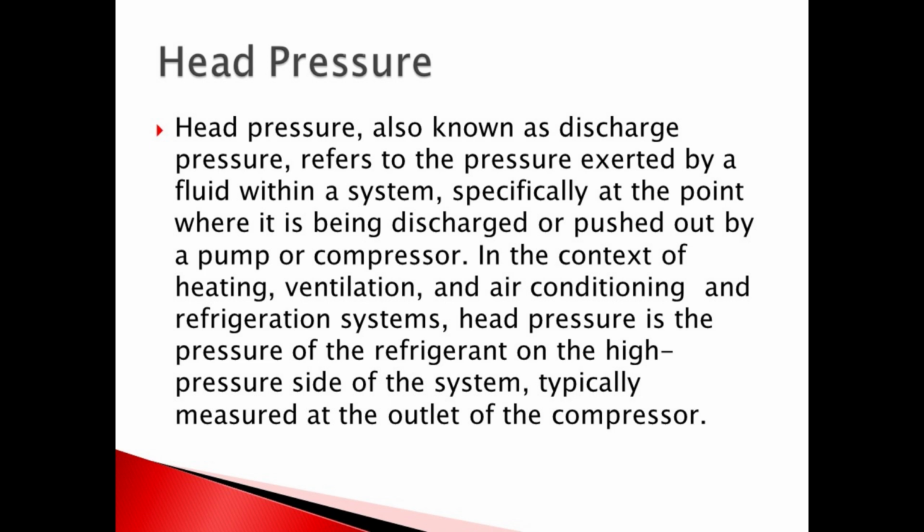What is head pressure? Head pressure, also known as discharge pressure, in air conditioning equipment refers to the pressure of the refrigerant as it exits the compressor and enters the condenser. This is a critical parameter in the operation of air conditioning and refrigeration systems. When the ambient temperature is very low, the refrigerant pressure will also be very low, leading to inadequate cooling performance. Additionally, there is a risk of liquid refrigerant returning to the compressor, known as liquid slugging, which can result in inefficient operation and potential system failure.